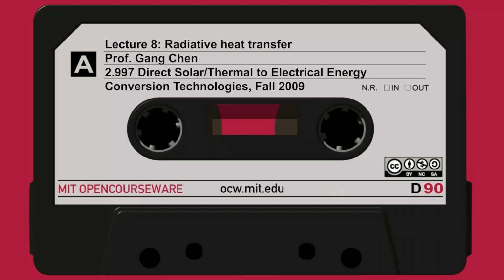So the black body Sun, and the absorber, if I absorb all the solar radiation, the absorber is also a black body. Say it is at temperature T, and then I put the engine in between this absorber and the ambient, with the output, and I can imagine this engine is perfect, a Carnot engine. So what would be the efficiency of such a system?